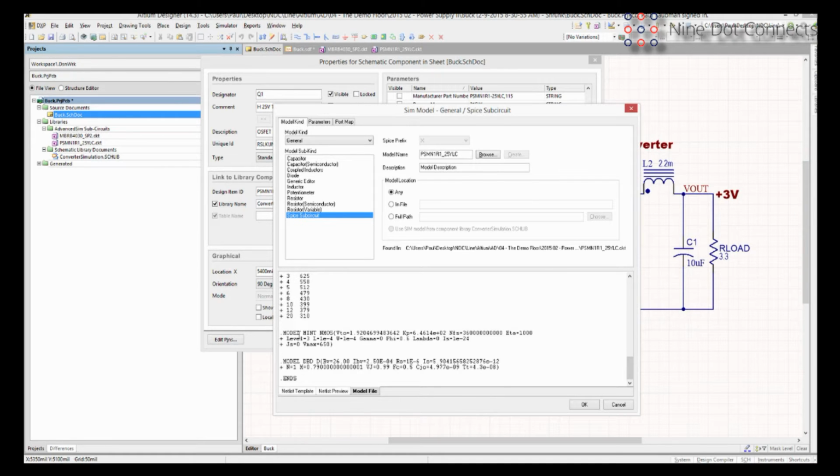So sometimes these models are provided as .MDL files. And so you have two ways of doing it: if you want to use a pre-existing model, you can certainly do so. The problem with it is that SPICE has a very definitive set of what models it can take in. And this gets a little trickier too because of the fact that there is a fundamental difference